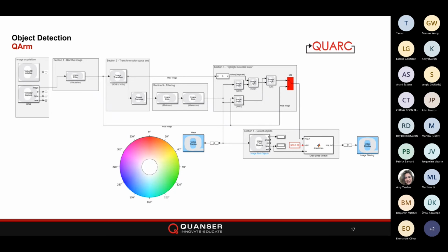I will first talk a little bit about our QUARC vision blocks and what they're doing in this simple example. Since we are using an RGBD camera, we need a video 3D initialize and capture block, which will allow us to start our camera and decide the output format and its resolution. Once we get the image, we filter the image to smooth out the edges. The image filtering block allows us to do other types of filterings, for example, maximum, minimum, or even toggle filters. We then convert our image to HSV to be able to do proper color thresholding.